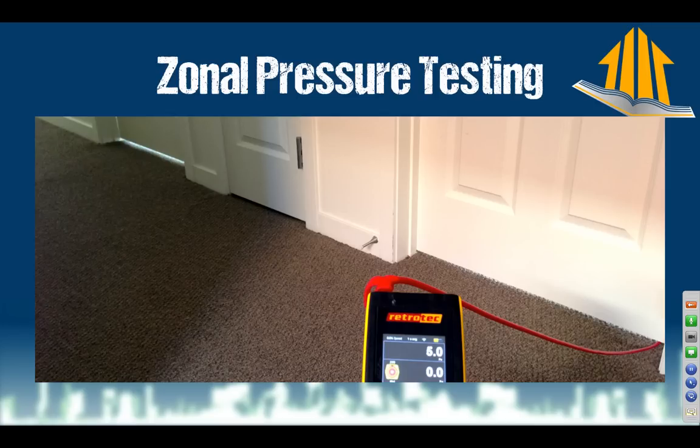You want to know what you are about to test and how exactly to run it before you start testing stuff. Because I have plenty of people call me and say, hey, I tested all the zonal pressures and they were all 0. And I was like, okay, did you close the doors? And they said, no, I just threw the hose in. Well, that's not a test. You're not testing anything. So you want to make sure that you don't waste 2 hours of your time.